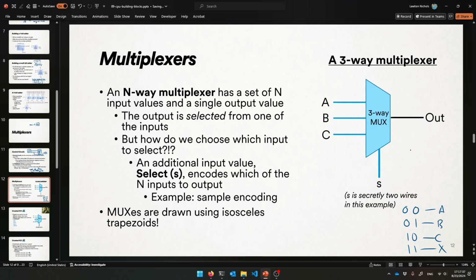All right. So you need 2 wires, 2 bits coming in, that is your selector, 2 bits to select, was it 0, 0, 0, 1, or 1, 0? And then you send that in as input. Let's say we want to select C, so we'll send 1, 0 in along our selector, and that will cause the multiplexer to take the C and send that into the output and cut off these guys. All right, that's the goal.